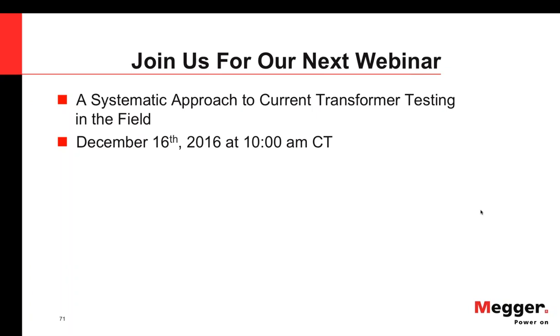This one's really specific. What is the effect of current distortion on elevator motors, or motors in general? As you have current distortion, what will happen is what I talked about before with the skin effect. As the magnitude of those harmonics and the frequency increase, you will generate more heat in them because you're increasing the skin effect, which is pushing the current more to the outside of those motors. So they will heat up, and obviously, the more heat you get, the faster they will deteriorate.